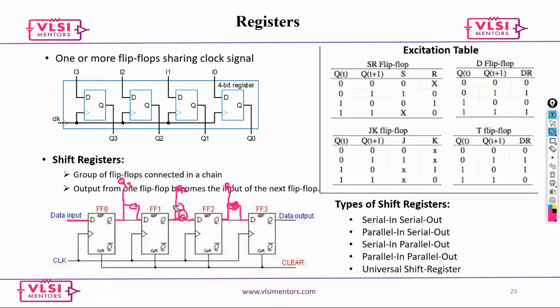You will have some combo logic for when the transfer is happening. Now input would be coming in, and all the flops would be loaded one after the other, and then you send all four out in one shot. So again, four cycles you load, and then you send all of them out. So that is serial in, parallel out, and parallel in, parallel out we just saw.